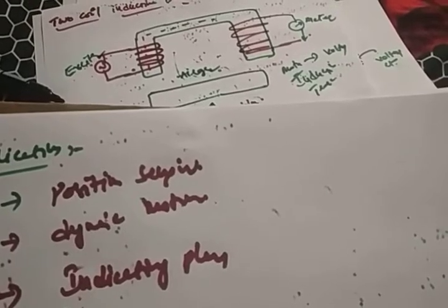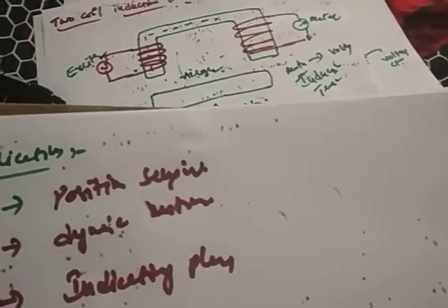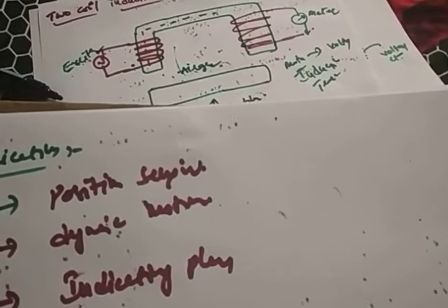Single coil type means that while changing the motion of the magnet, the air gap will be changed. Due to that, there will be a flux change, and whenever the flux changes, the inductance changes. The changed inductance can be calibrated by the scale, and the output of the scale is analogous to the motion that you applied. That means the motion is converted to an electrical quantity.